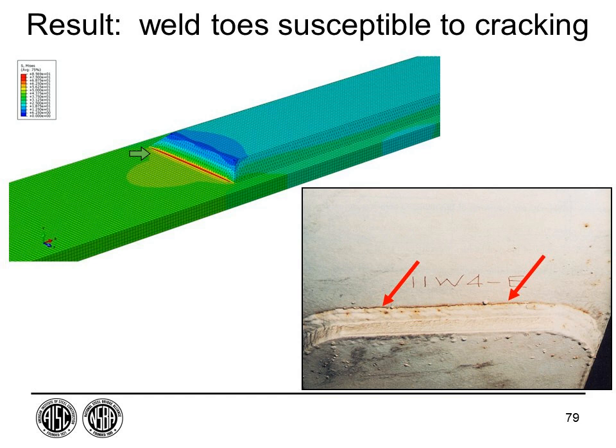evaluation. I will say, without a doubt, the best way to do any fatigue evaluation, if you're running into problems with life calculations on existing bridges, is pay the little bit of money to put a few strain gauges on the bridge and let the bridge tell you what its remaining fatigue life is. Because generally our estimates are quite conservative.